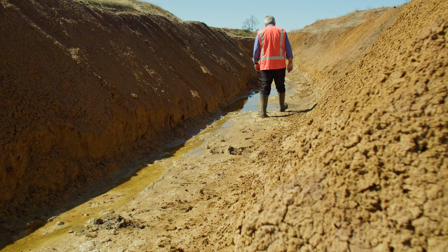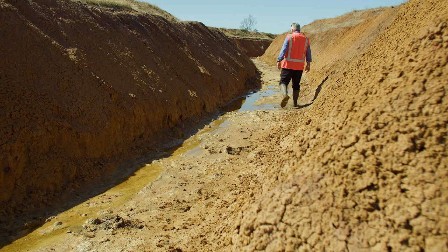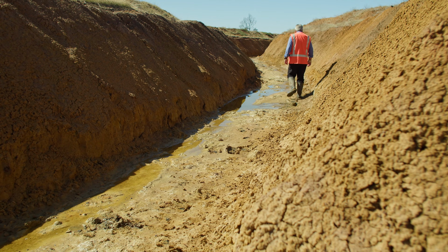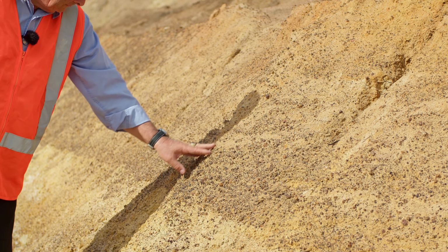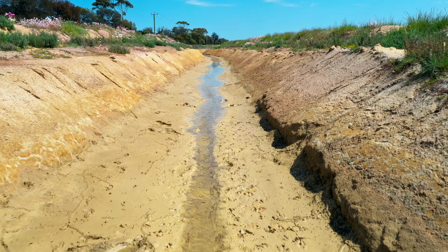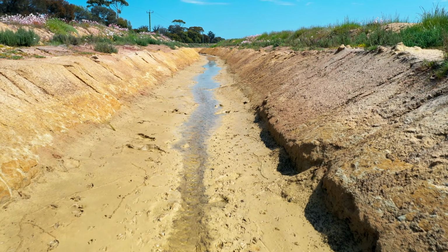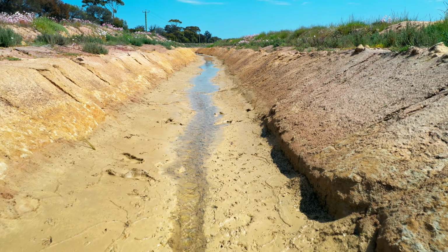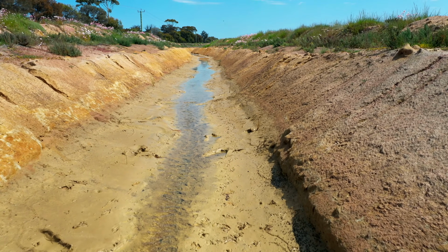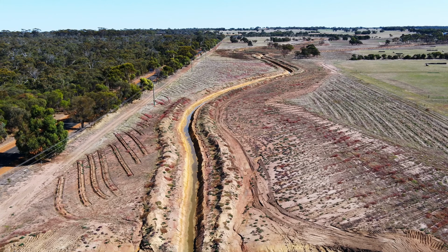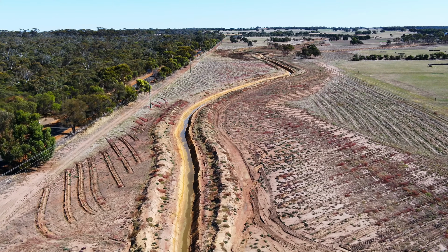They may be up to something like about 60 or 75 degrees. When you're talking in less stable soils, we like those slopes to head back towards about 45 degrees. In very poor soils, the slope of the side batter may be extremely low and go down to as low as 15 degrees. Having said this, you can move another couple of metres along a groundwater drain and you encounter a different soil type again.